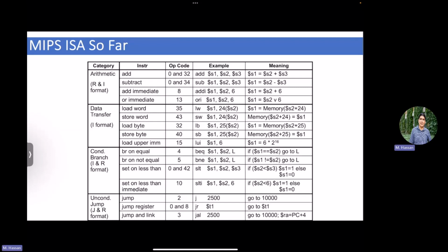By the way, Intel had a divergence from what we are saying: even in early 32-bit machines, they had a way to combine two registers together to form a 64-bit operation. For example, if you wanted to add 64 bits, you would use two registers together as lower and upper. It was a very complicated way, right? And it also eats up a lot of registers. Instead of having two operands, you need four registers. Right? But this was an Intel thing to enable high performance without increasing the machine width.